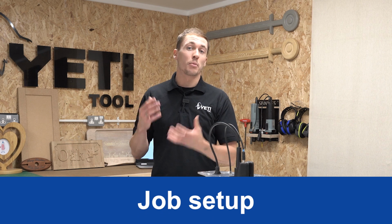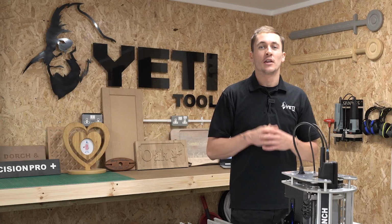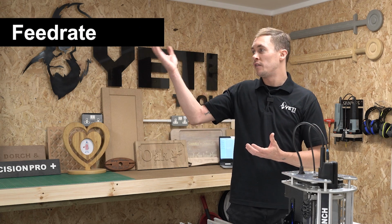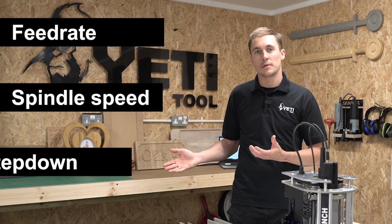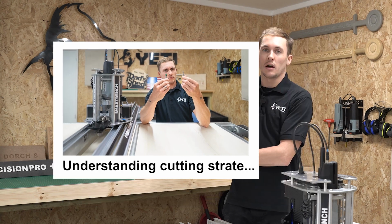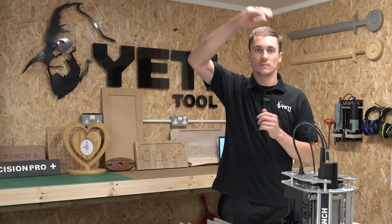The first step is to prepare your job file, and in this video we'll be using Vectric VCarve Pro. The critical strategy parameters for YetiPilot to perform are feed rate, spindle speed, and step down. If you are at all unsure on what these terms mean, then please check out a guide to understanding cutter strategy which covers these terms and more.